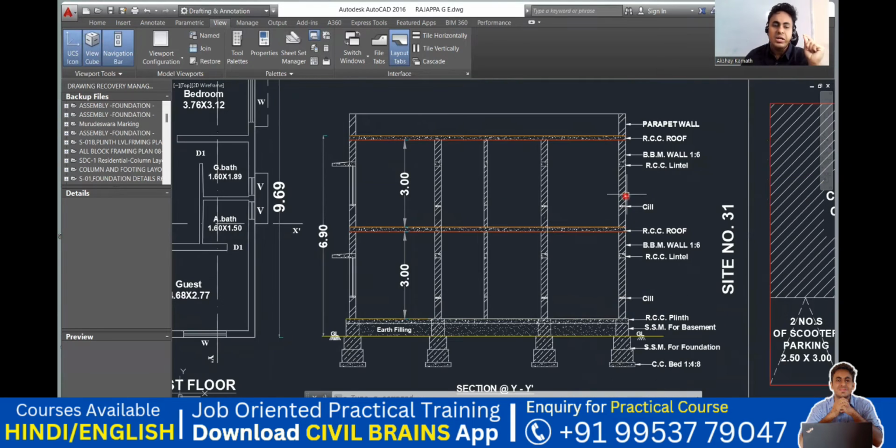You got an idea? The total height of your building from the ground level to the top of your roof is 6.90 meter. That is 3 meter plus 3 meter, and then you're supposed to add this much height, which comes out to be around 0.9 meter, which is 900 mm.